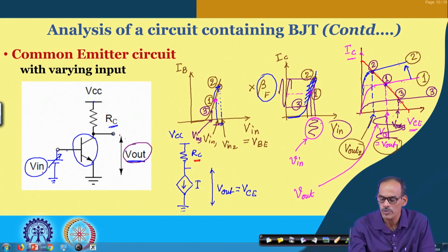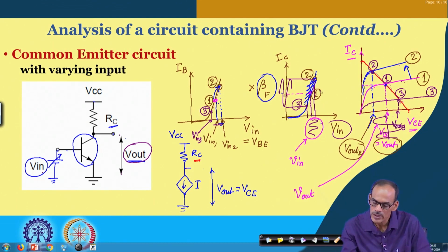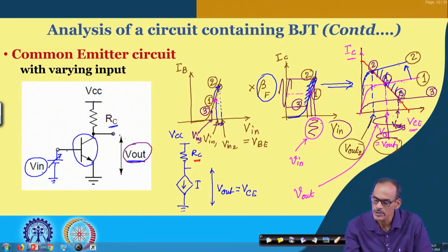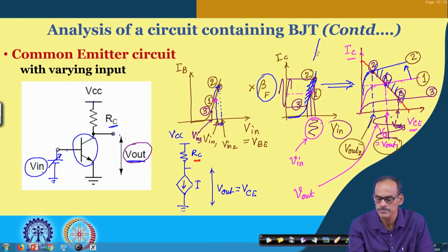Depending on the slope of this line, you can see that for a given variation here there is good amplification, and then this variation comes to this y axis, and the load line works as another mirror working in the opposite direction, namely converting current into voltage. So, if the slope of this mirror is very stiff compared to this mirror, then we will be getting the amplification.